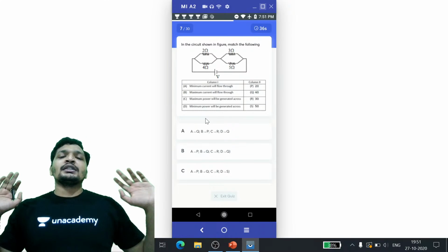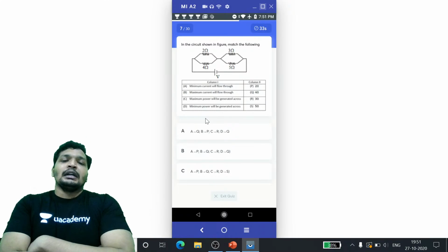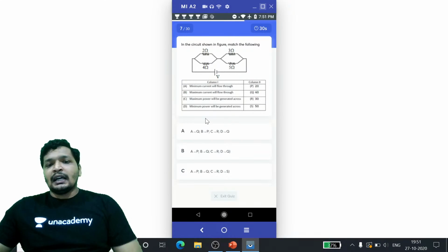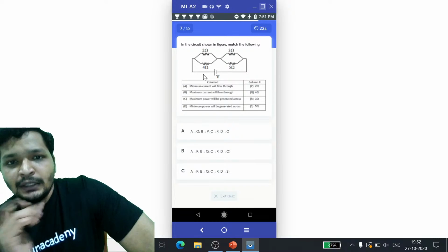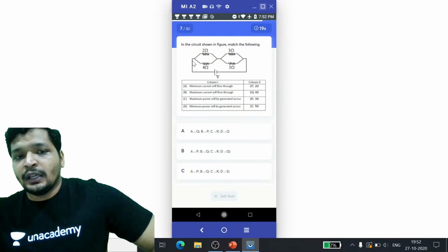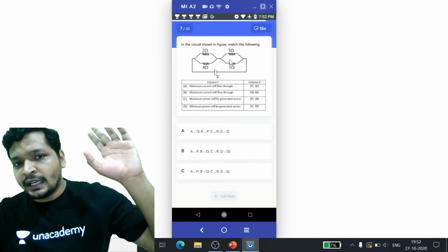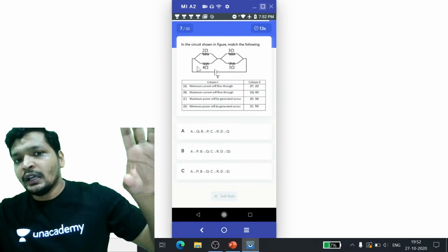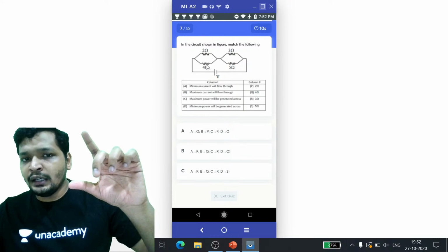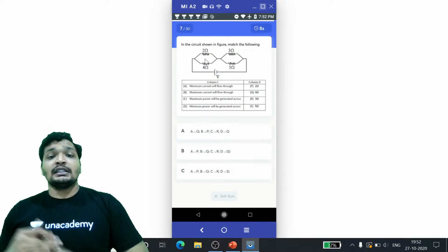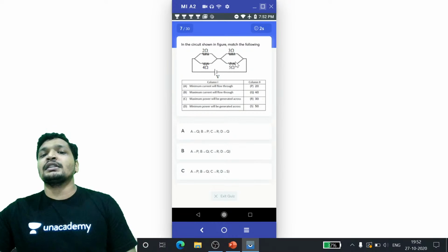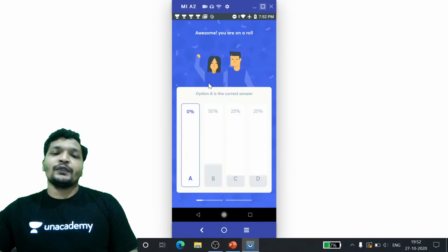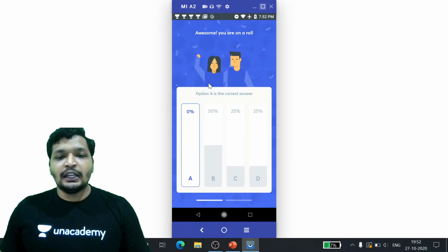Okay, now let's think about it in a very different manner. So this is a connected node. Some current I will be entering over here, and it will get divided; the total current flowing is I. Here also it will be I. Just notice this. If you are attending the quiz, attend the quiz. The concept is very simple. If I is going to flow over here, how is this I going to get divided? In the reverse ratio of the resistances, since it's a parallel combination, right? So go by the ratio of the resistances. For example, in this case, A should have been the answer.